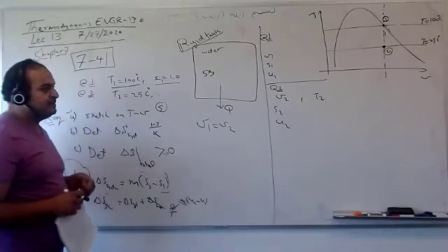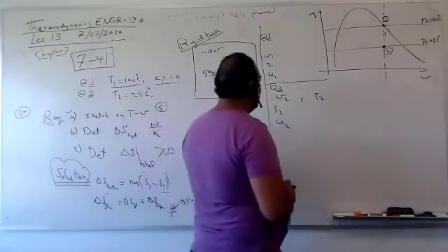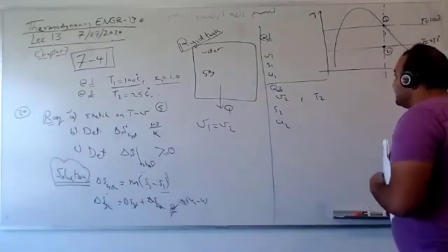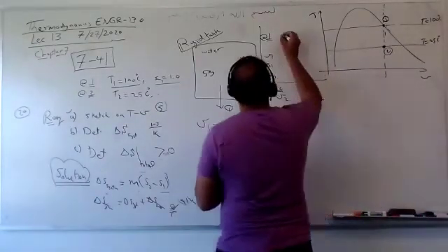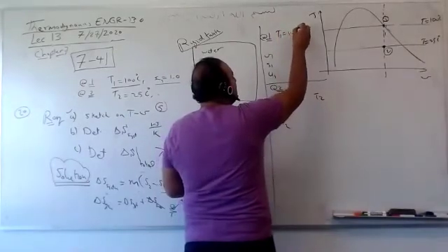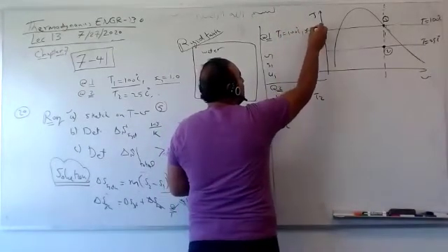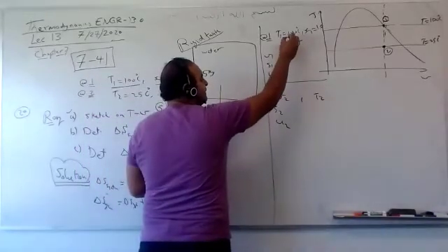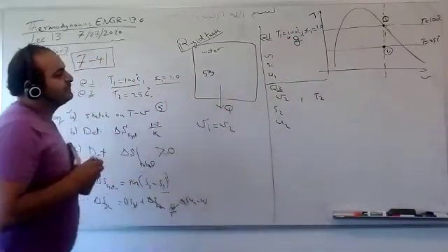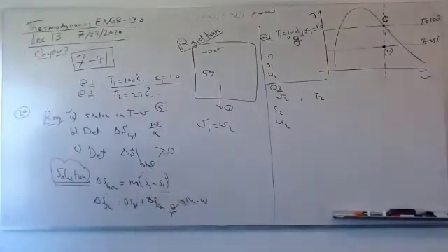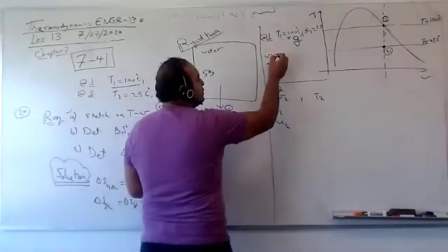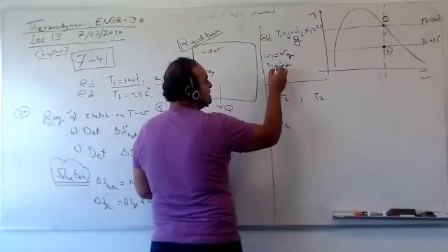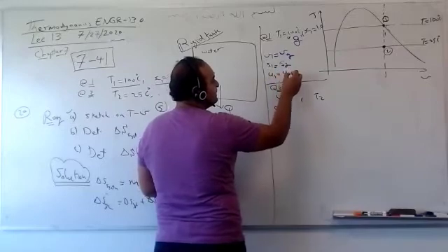Okay, guys? Because sometimes you have interpolation. Sometimes you need to do quality calculation. That's not easy. So at state 1, where I have T1, that's very easy. T1 is 100 Celsius and X1 equals 1. It means use everything with the letter G, the vapor. So V1, at this temperature, use VG, SG, UG.